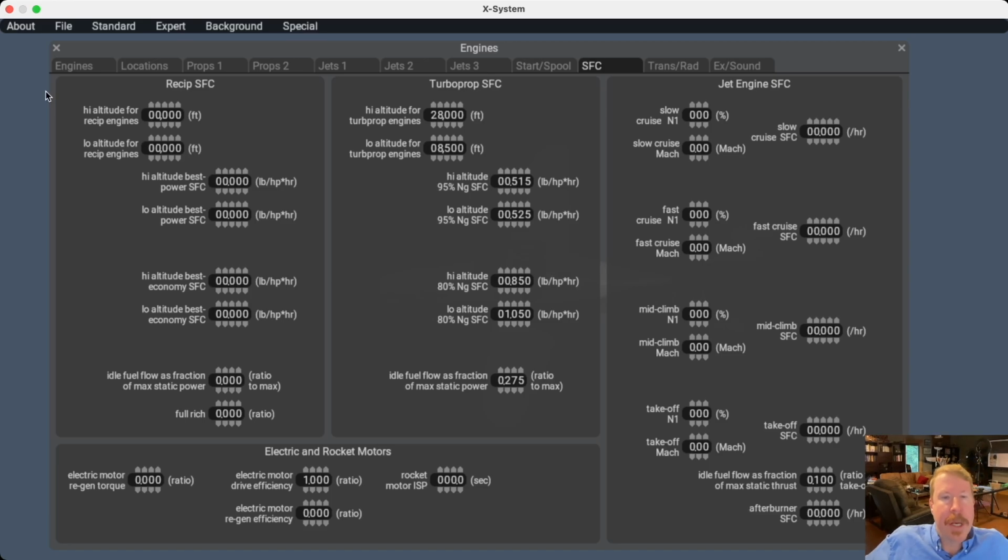And here's why it is. Remember, with a reciprocating engine, the air is actually compressed when this piston is moving up and down in a cylinder. Does it matter how fast that piston is moving? No. The air gets compressed, the fuel gets added, it expands. It doesn't matter how fast this is happening. I mean, the engine can run this slow. It wouldn't matter. The same compression and expansion are all in play because the gas is in an enclosed space.